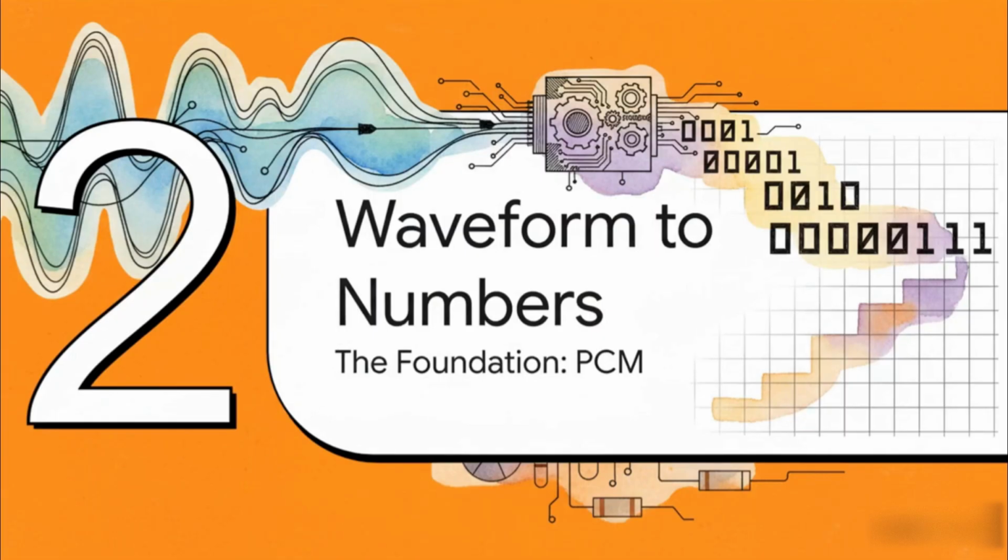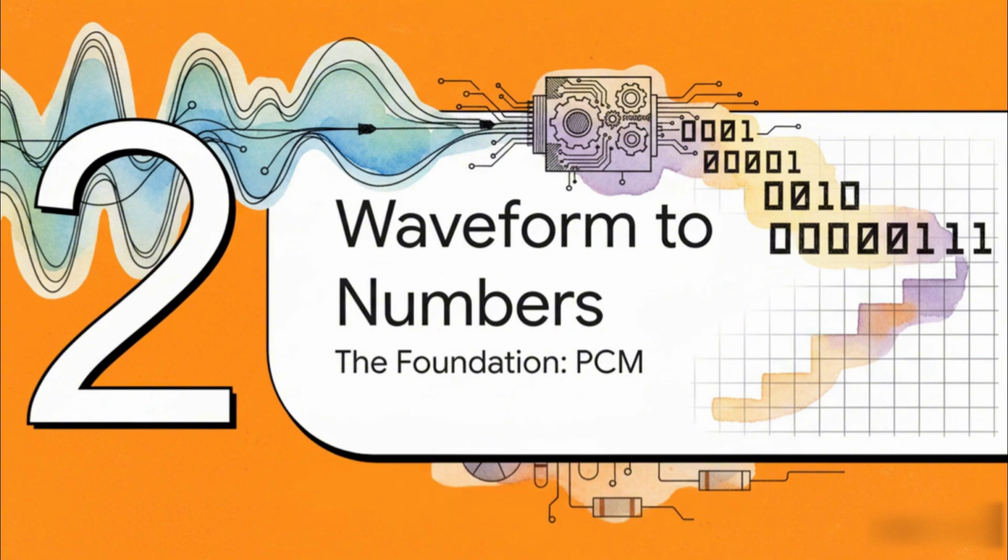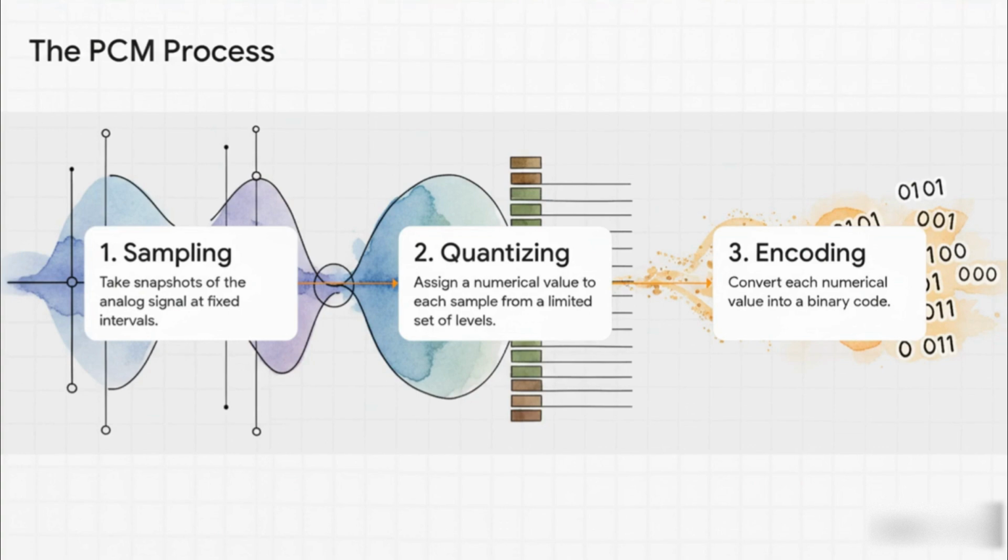So, let's get into the nuts and bolts of PCM. How does this fundamental method of turning a smooth wave into a bunch of numbers actually work? Well, it's basically a three-step dance. First, you've got sampling, where you take all those snapshots, thousands per second. Second, you quantize it. This is where you round off the value of each snapshot to the nearest level on a scale you've already defined. And finally, you encode that level into a binary number, a string of ones and zeros.